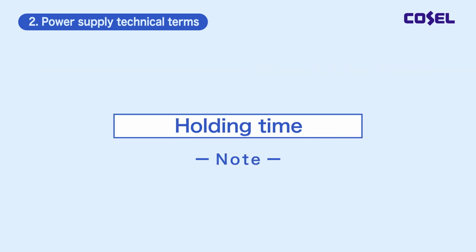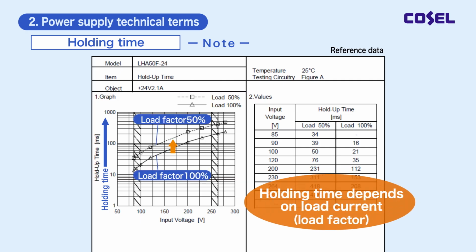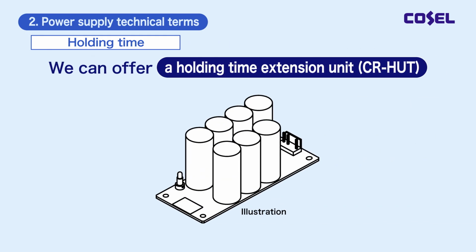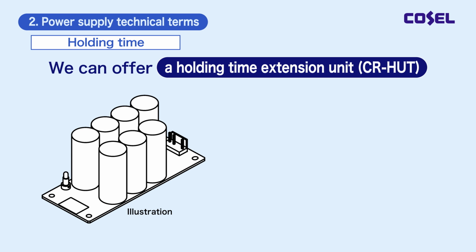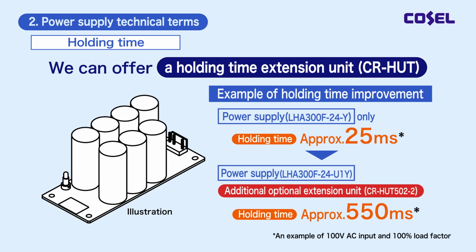A note on holding time. Holding time depends on the load factor, and the lower the load factor, the longer the holding time, so please check the property data. For some bare board power supplies, we can offer units that can extend holding time. Please take advantage of these products, as they can greatly improve holding time.